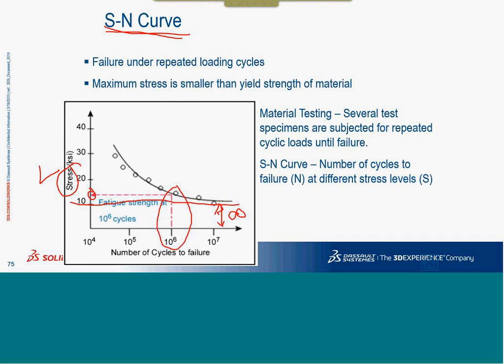So one way to see this: fatigue analysis is actually a post-processing option, whereas the static analysis, F equals k times x, is more about solving. The question comes, we know the stresses from there. In fatigue analysis, we compare those stresses with the kind of loading cycle, the mean stress, and the stresses all over the body are compared with this SN curve, and we come up with the life expectation at different locations.